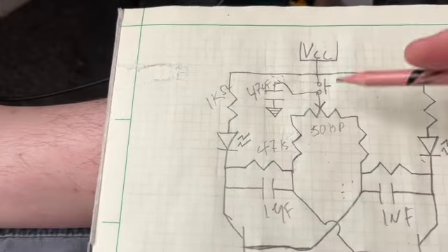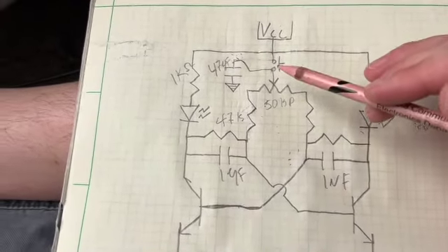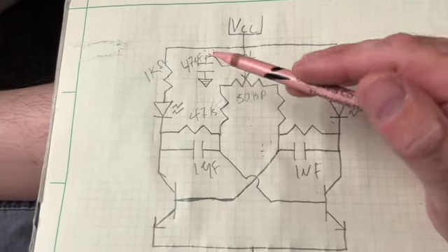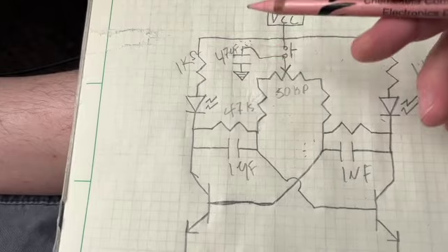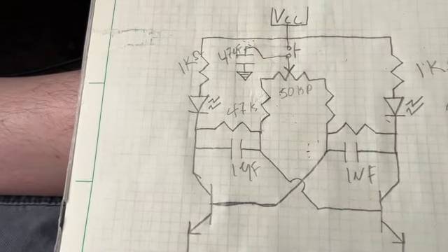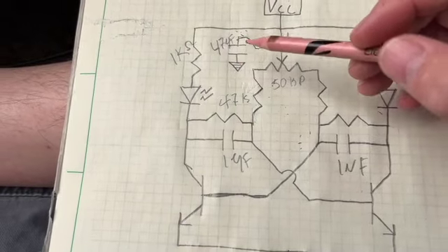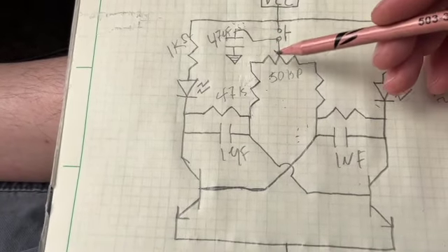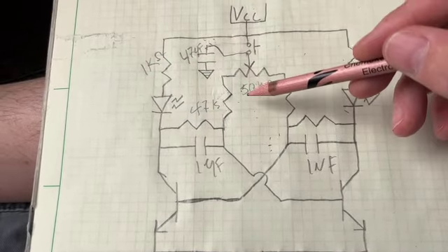When you press the button, the capacitor is instantaneously charged to 9 volts. It's in parallel with the voltage source. And whenever you have two things in parallel, they become equally charged. So this capacitor becomes charged to 9 volts the instant you push this down, which means when you let go of the button, the capacitor begins discharging.